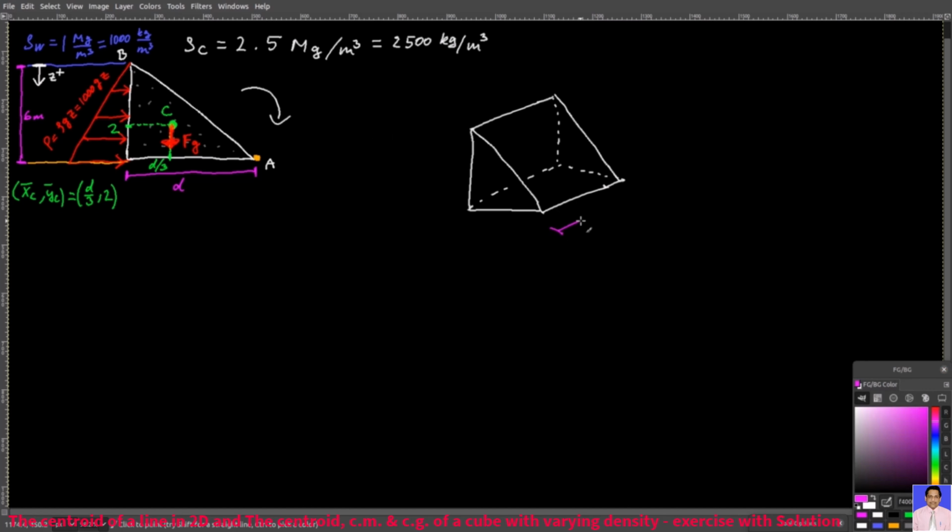And so if we say that this is the length of the dam, even though in the past we referred to it as the width, but let's refer to it as length now. It doesn't matter. And so I will take my pressure function P and I will multiply it by L, whatever it might be. So P is newtons per meter squared, L is in meters, and as you can see, I will get W, which is newtons over meters. So it will be 1000 times L times g times z, newtons per meter.